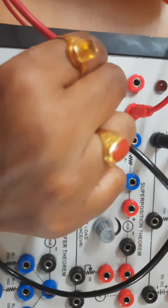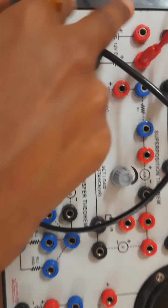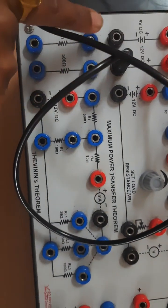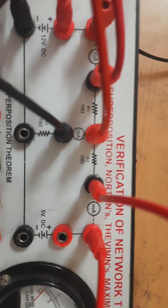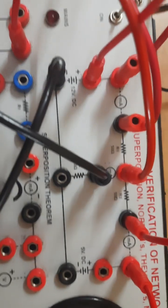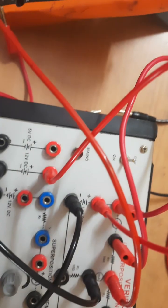And remember one thing, we should never short this terminal as we are deactivating the 5 volt supply. That means if these two terminals are shorted, then the supply voltage 5 volt will be directly shorted. So this should not be shorted. We should short here in these 2 points. Okay, so we are shorting here. Now 5 volt source is shorted.